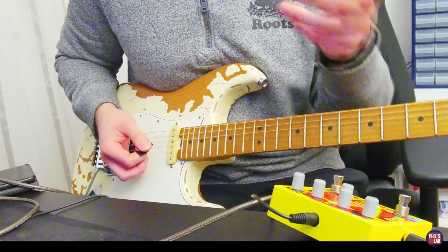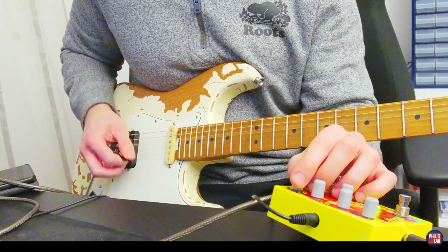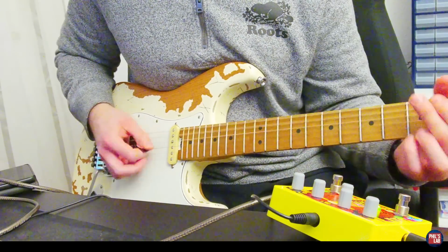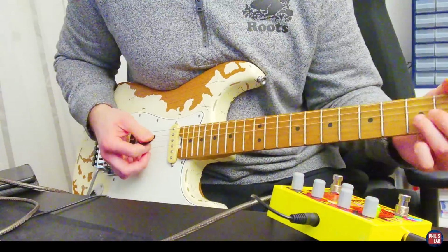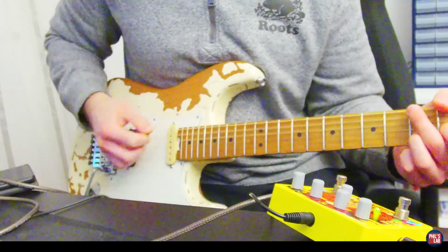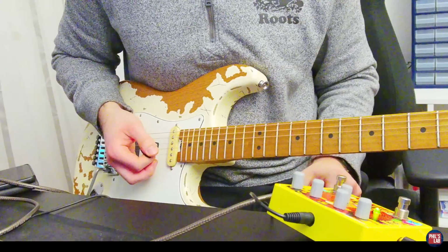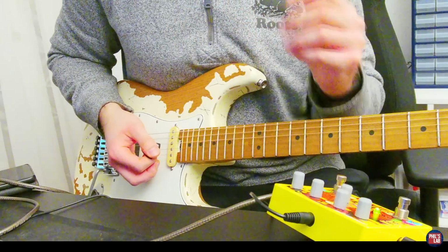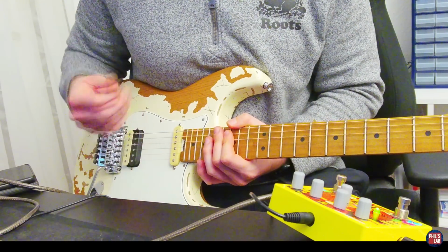So you can really hear it changes the characteristics of the distortion quite a bit from this rather full sound to this bit more tinny sound. So it might be cool to play around, blend them in between a tiny bit. But such a simple algorithm, we can get quite a lot of different sounds out just by making some of these parameters variable. We can play with the filters, cutoff frequencies, and much, much more. So I think it's quite a cool, simple demonstration of what we can do with DSP.